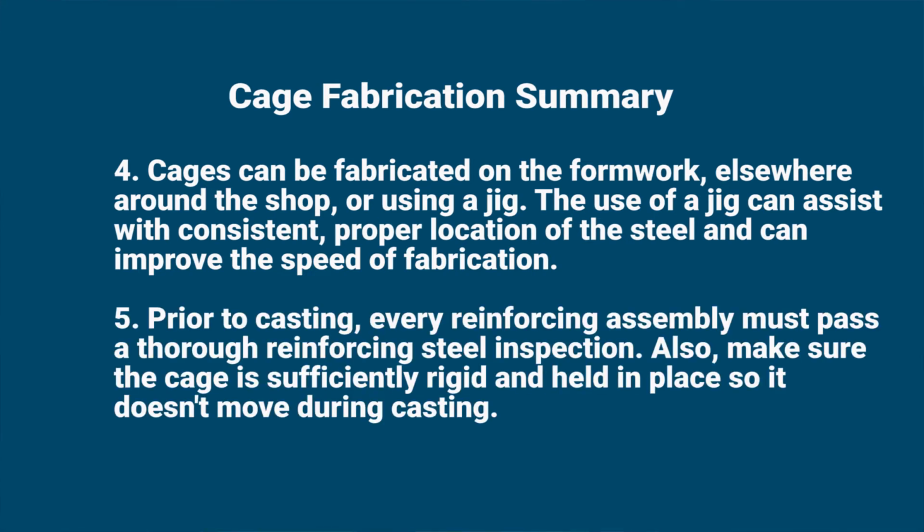And 5th, once you have the cage in place, give it one final inspection to make sure that the tolerances are there, the concrete cover is correct, and that the cage is rigid enough that it will handle the concrete casting and vibration and won't move during that procedure. After that, it's all easy, so keep on precasting.